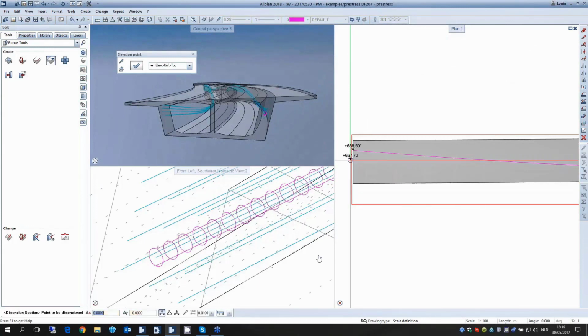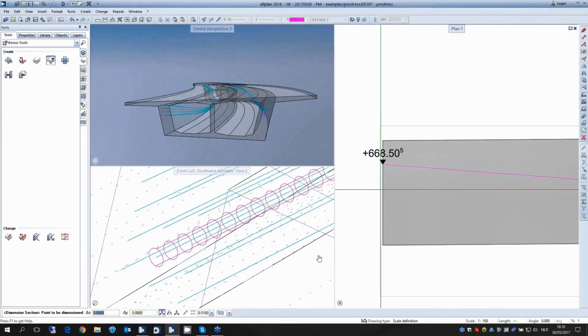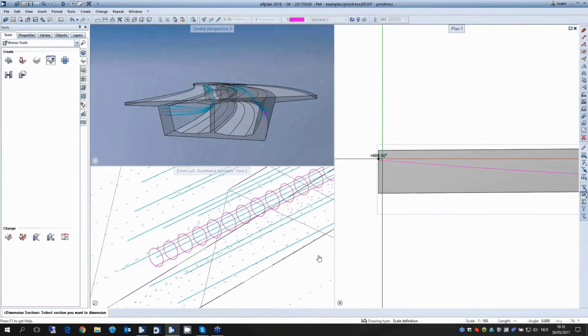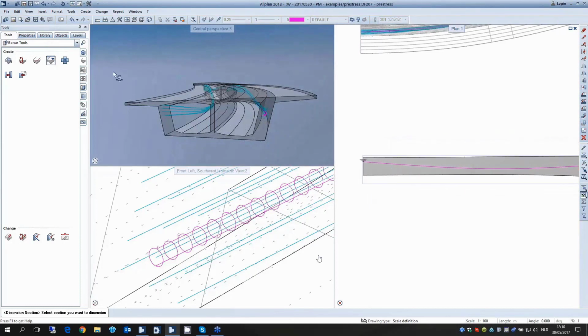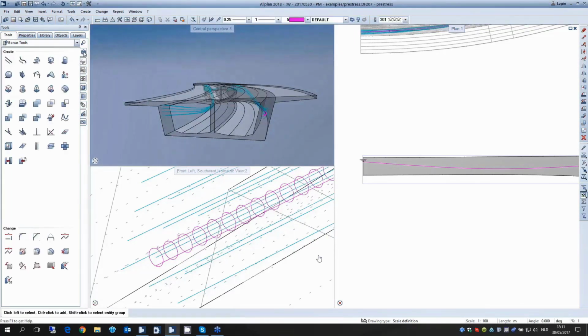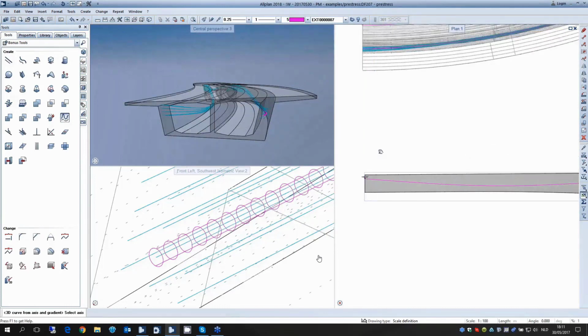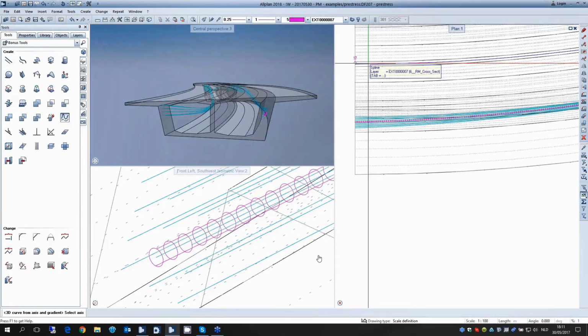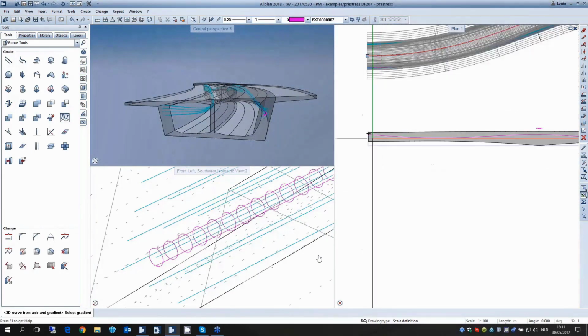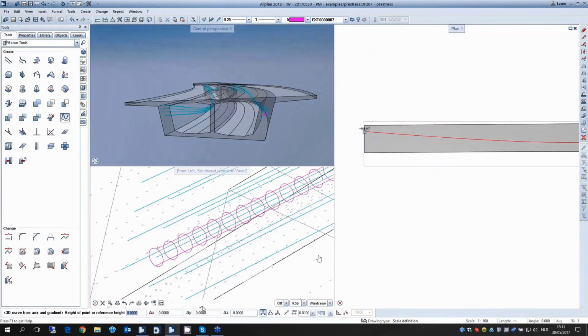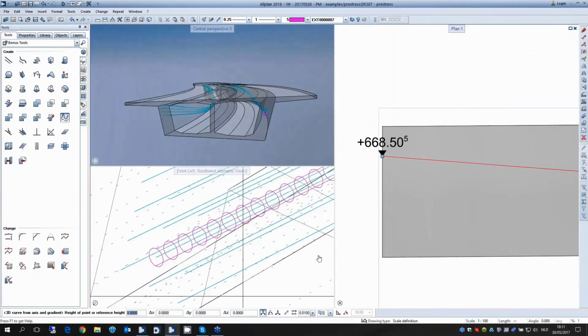It's kind of interesting that in the beginning we start with a horizontal curve, a vertical curve, and we combine them up, and then when we go to do PT, we're essentially taking our horizontal curve, applying a new vertical curve in order to get the geometry for the PT duct. But it is really just the way that makes sense when you're operating on it. You have your bridge, and then you're going to want to reinforce it later, and you don't know what that vertical curvature looks like until a little later in the project.